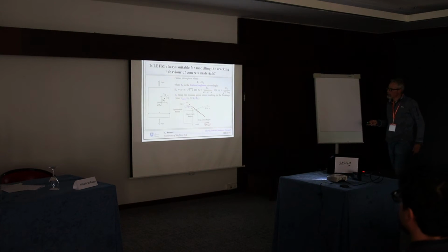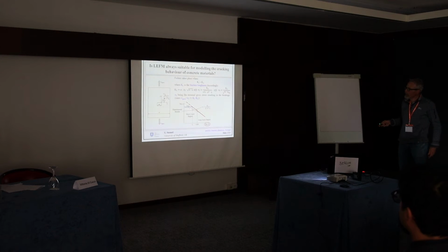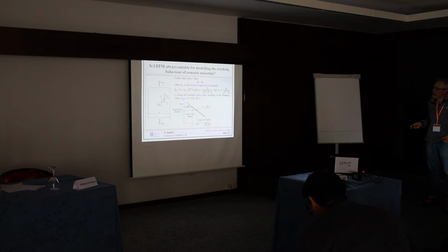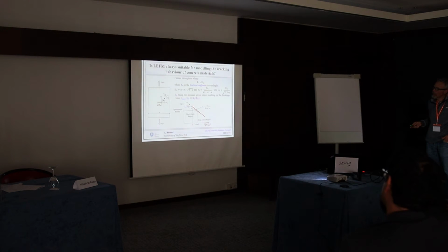we can plot the strength in a graph like this one. And actually the red line is the line we would get by using this classic formula based on fracture mechanics. So according to this formula, as the size of the defect or the equivalent length of the defects decreases, the strength increases. And in theory, we would keep going and going and going, because this is a log-log representation.